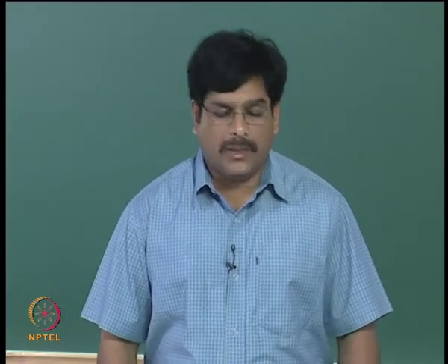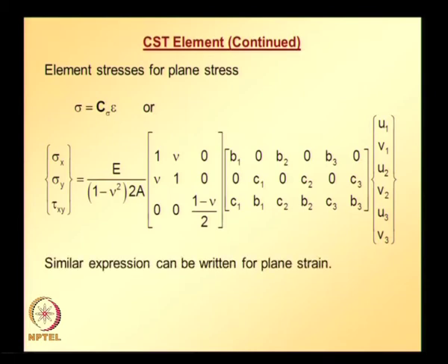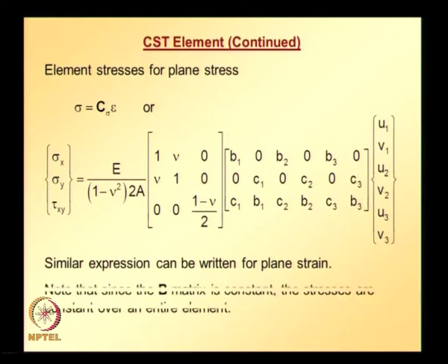We need to use the corresponding constitutive matrix. So, if it is for plane stress, this is how you can calculate. Similar expression can be written for plane strain case. And note that since B matrix is constant, stresses are going to be constant over the entire element.